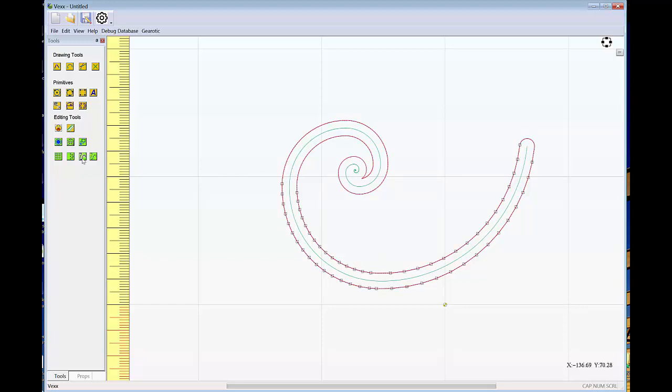Now there are buttons over here on your editing tools for converting to arcs, Beziers, and lines, or converting back to line segments. If I convert what we have on the screen now to arcs, Beziers, and lines, you can see it converts fairly well. The shape is primarily preserved, but there are always mathematical ambiguities that can cause these arcs, lines, and Beziers to not conform to the exact shape that you want. So it's something to keep in mind. You can turn that off, or you can shift things back into lines with the line switcher, but it can make it harder for you to edit.